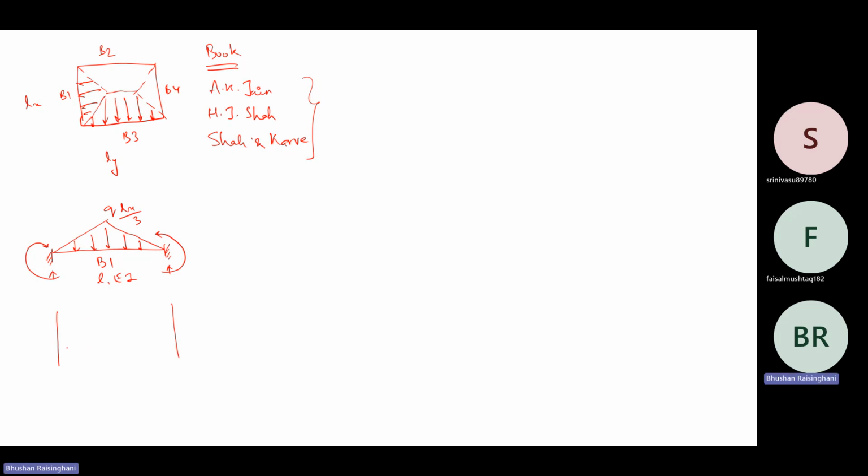Okay. So this way, this was anticlockwise, this moment will become clockwise. Finally, the reaction will be also like this on the column, right? And this is, let's say, for story number 3. The same will repeat for story number 2 again. So you just have to understand this free body diagram. From the beam, the reactions are transferred to the column, then again reactions at the bottom will go up to the footing level. There will again come a beam here at story number 2.